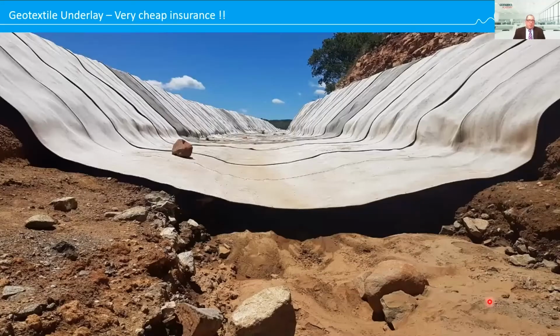Okay, and here's an example of what can happen if you've got no geotextile under a GCCM. This is a channel lining application. Further up here, there was a breach, there was a problem with one of the jointing systems. I think someone accidentally punched a hole through it with the machine. That night it rained, and as you can see, all the fines were washed out underneath. If there was geotextile under there, it wouldn't have washed out.